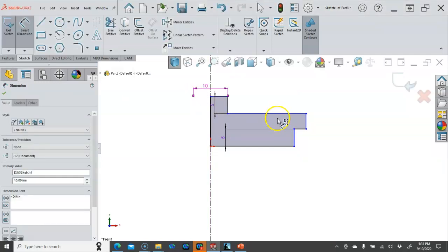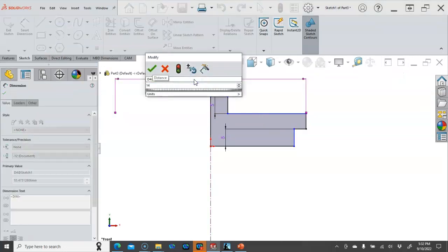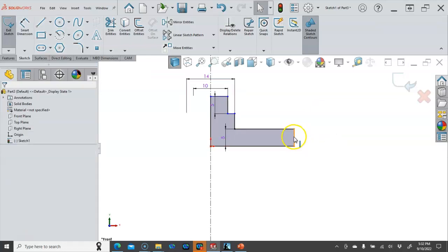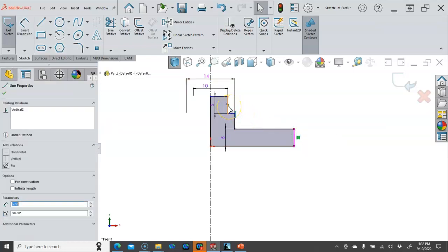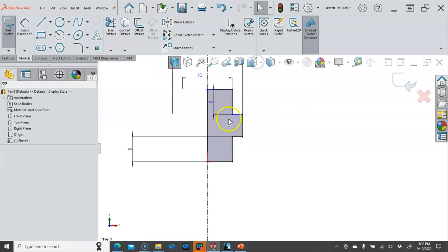So that is 10. And because I just did a diameter, it's going to say you must want to do another one, so here you go. And in this case, I do. And I could come back here and tell it to do the last one, but those are going to share the same dimension, or my design intent will be that they share the same dimension. So select, Control, select, make that collinear.